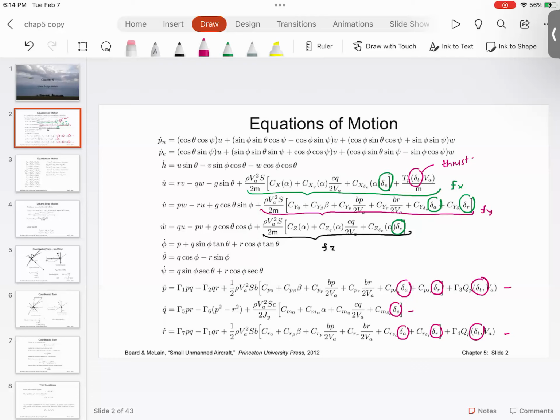You can manipulate those 3 forces, 3 moments, and thrust using the control variable, which is the physical deflection of the control surfaces and changing the speed of the prop. Everyone understood this? So now this chapter deals with something called linear design models.